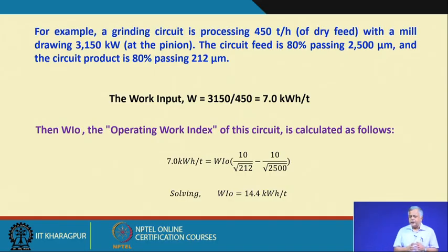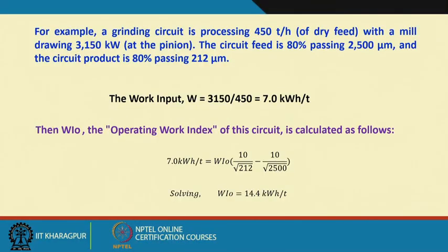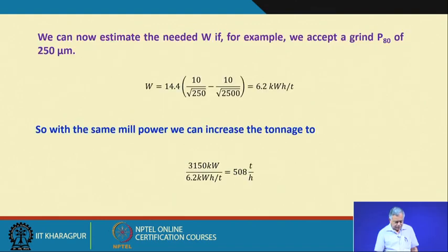So, you say that we are consuming a lot of energy in my milling circuit, that is your grinding circuit. So, if I increase this 80% passing size to 250 micrometer, first let me discuss with my processing colleague to show how much energy we essentially will be saving.